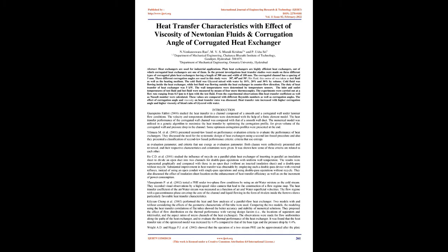Hot fluid, thin motor oil, was taken as test fluid as well as the heating medium. The cold fluid was glycerol mixed with water by 10%, 20%, and 30% by volume. Cold fluid was flowing inside the heat exchanger, while hot fluid was flowing outside the heat exchanger in counterflow direction. The duty of heat transfer of the heat exchanger was 5 kilowatts.